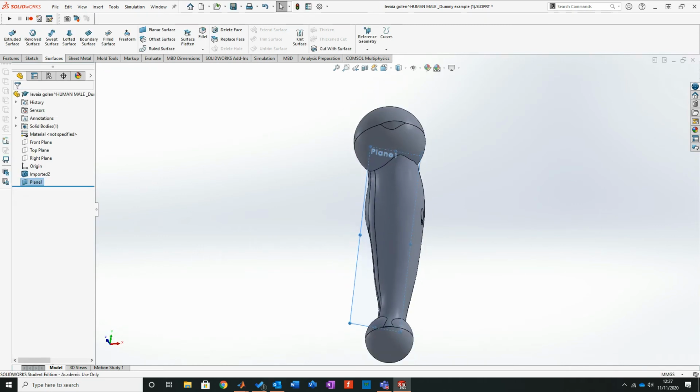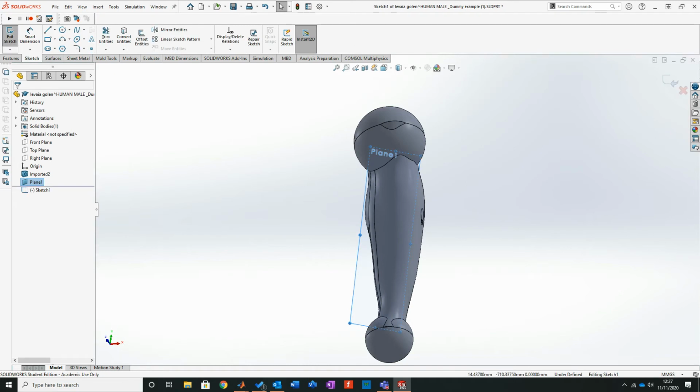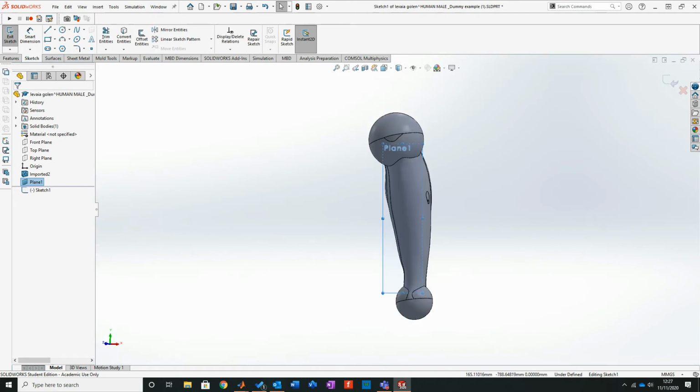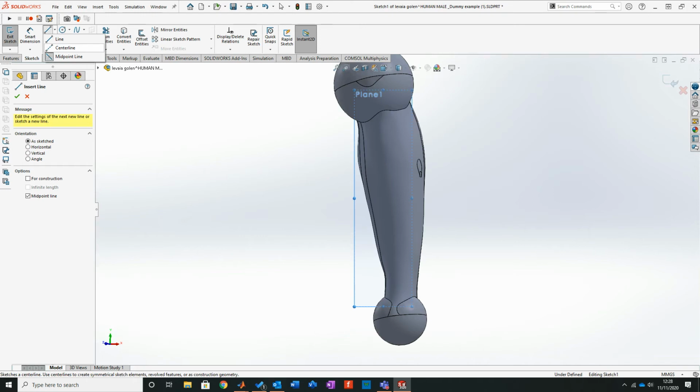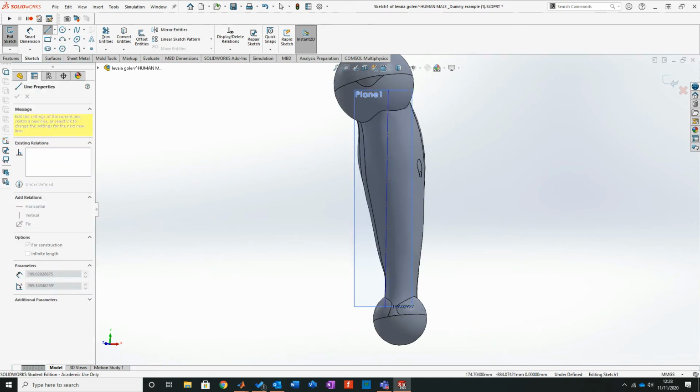Then with that, I'm going to go sketch and sketch, Control and 8. And really what I want now is something to allow me to project this way as well. So I'm just going to go here, go construction line, and bring this down, which is, I mean, I could go there to capture that edge even better. But no, what we'll do is we'll go completely horizontal and then click OK.